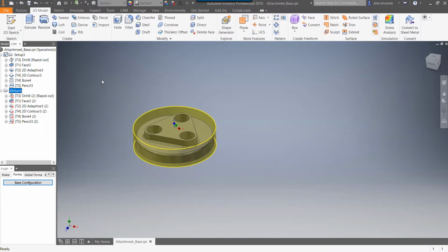So that's where you want to start taking a look into 3D toolpaths. I'm not going to get into the whole background behind 2D and 3D, but really the gist behind 3D toolpaths is that it's driven specifically off of model geometry, right? So if you're driving a toolpath from model geometry, that means this model can change between 2, 3, 4 different attachments, and it's not going to care, right? As long as the geometry is there and it's a fine geometry, then it's going to be able to generate some sort of toolpath.